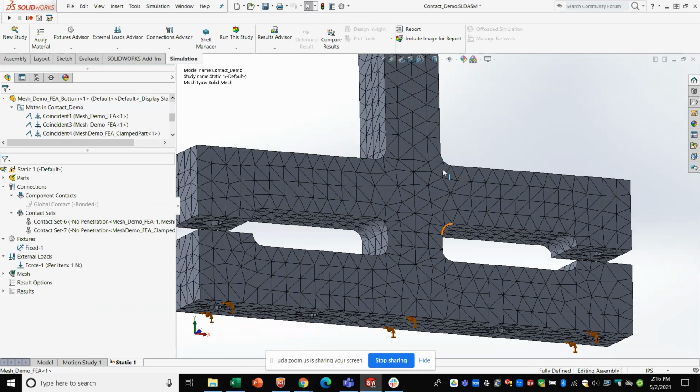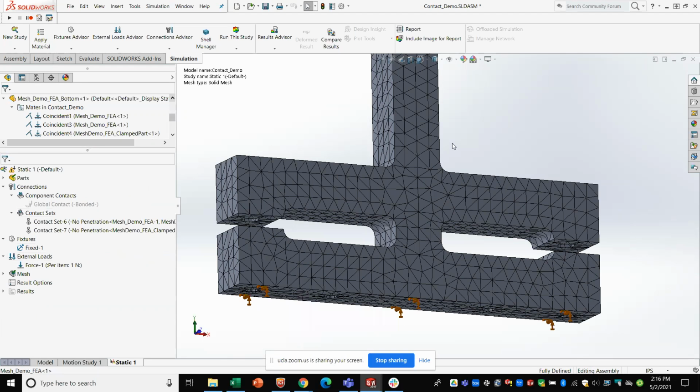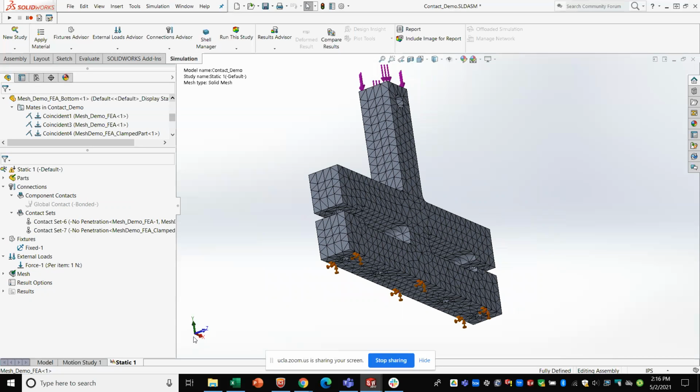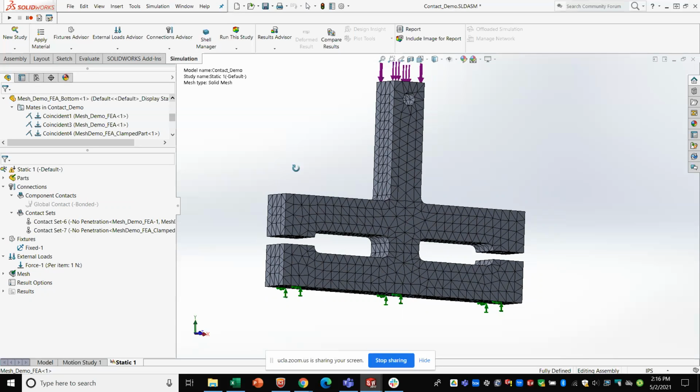And this is one of the difficulties that you'll run into with contact problems when you're first starting out, is that you still need to consider your part's constraints in all 6 axes of motion. That is to say, you've got motion in the X, Y, and Z translation directions, and you also have rotation along the Z-axis, X-axis, and Y-axis.